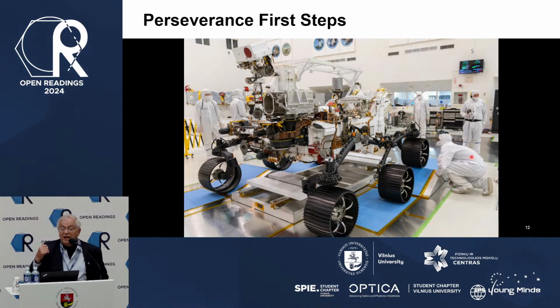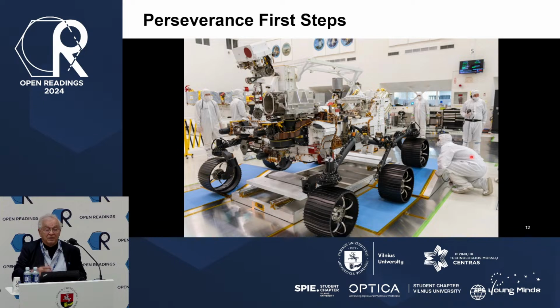So we avoid having any soldering. There is no soldering on it. So basically, we machine everything. If you take the wheels, we actually take a block of aluminum and we machine it. So we don't have any soldering. The same in the box which contains the electronics. So it requires a lot of challenge of figuring out thermally how you design the rover.